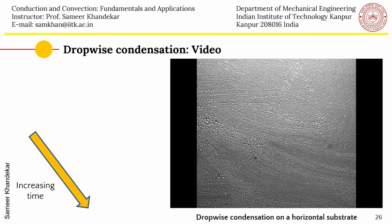I will now make the video a little faster, and now you can see bigger drops which are formed, and these drops are coalescing, and then surface tension is making them as circular as possible. They are trying to minimize their surface area. And then when the virgin areas are formed, you can see new drops being formed there in these zones. Let me go a little bit more ahead, and now you can see still bigger drops are getting formed, and they are growing slowly now, because the heat transfer has reduced through the larger drops, because as you will appreciate, the thickness of the liquid is now high, and the conduction heat transfer is difficult. And in the new virgin areas, a new generation of drops are being formed.